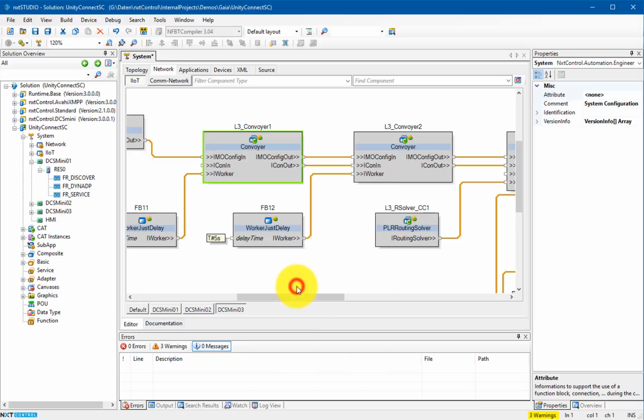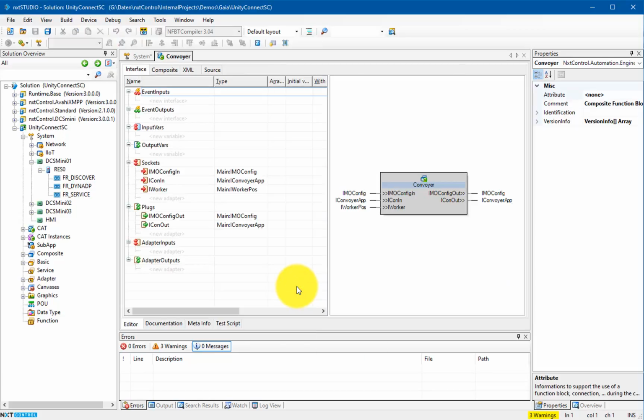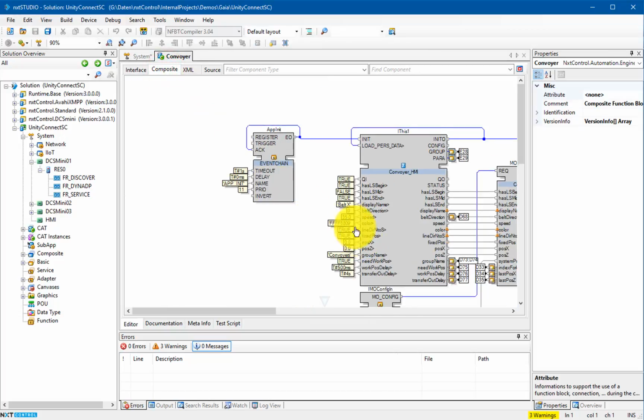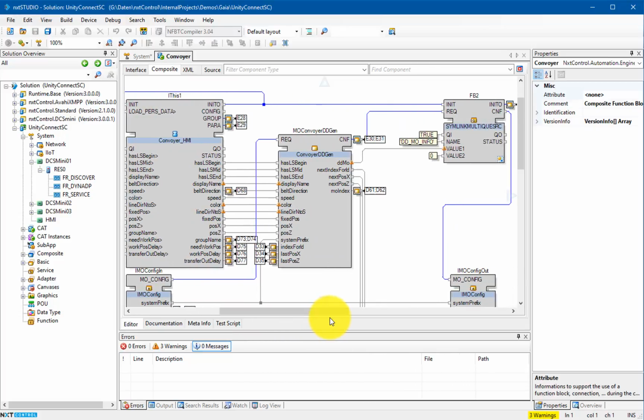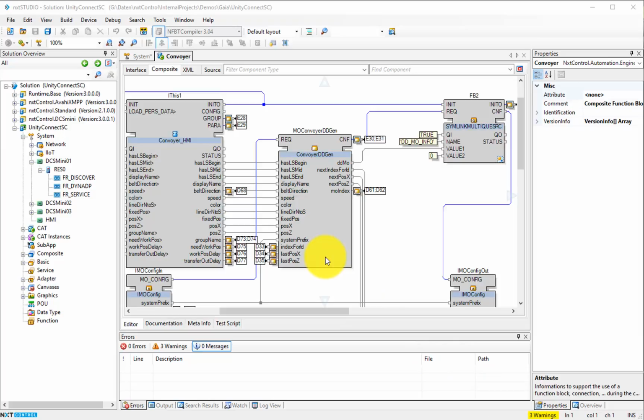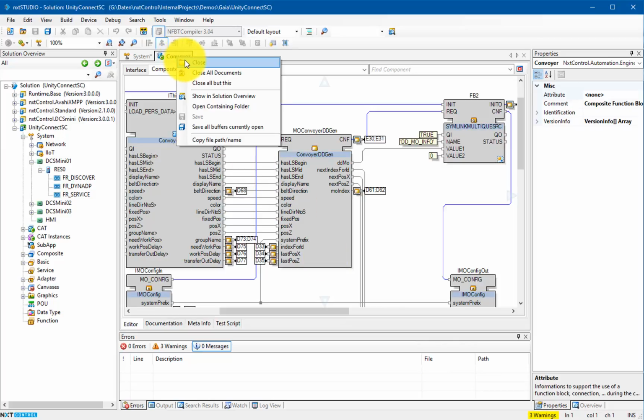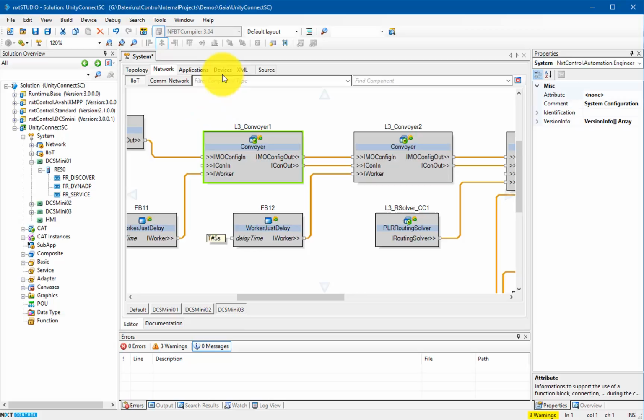Each application object function block, for example for a conveyor, generates the part of the service self-description that relates to itself. The object uses configuration data given by the user through the HMI, data resulting from the application structure within a single controller, or static data coming from the type definition. The partly generated self-description will be registered into device self-description storage as soon as the application gets deployed and started.